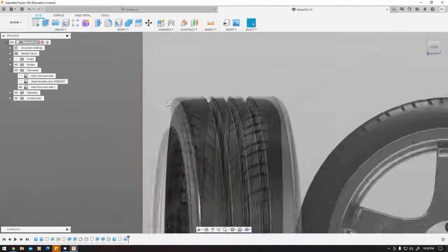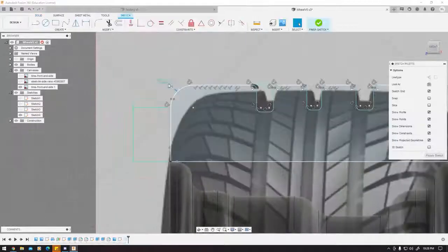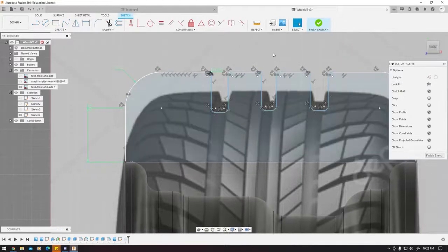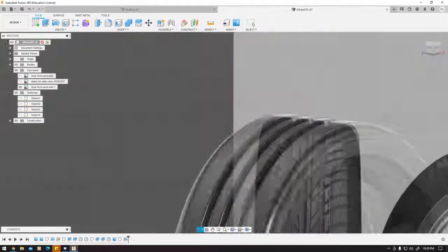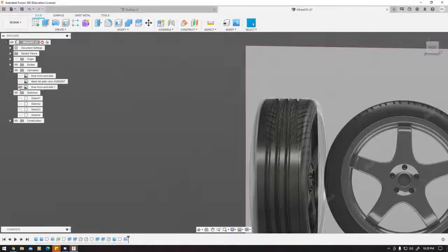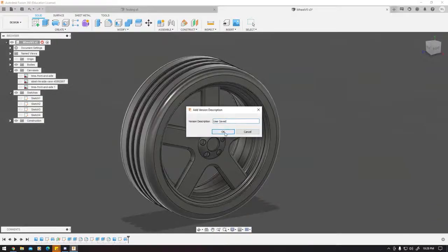Now if you want to go edit, it looks a little bit strange. We can just go back to sketches, double click our sketch, and I want to edit my radius. So I'm going to put 0.02. And it made it taller because we have it fixed, but we could always reduce that to 0.02 and press OK, and there's more radius. Hide the sketch or the picture, and I can press save.